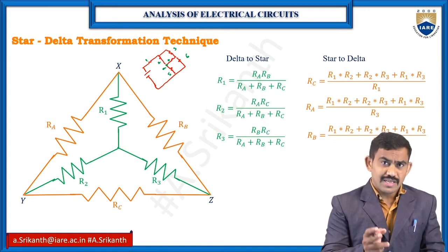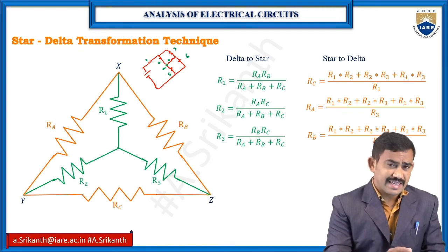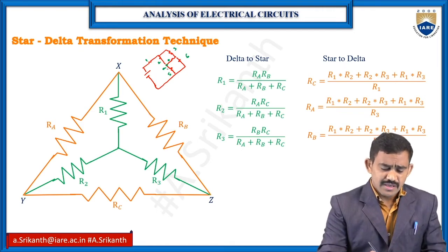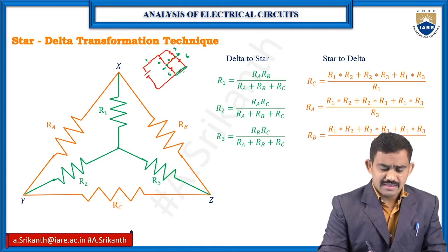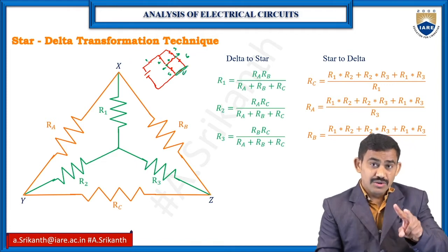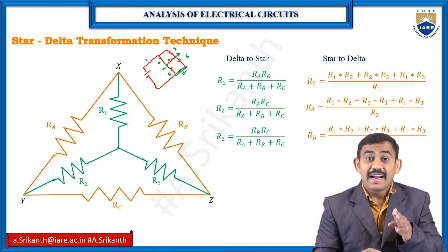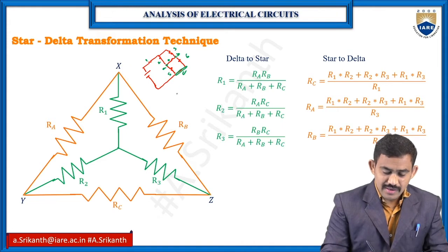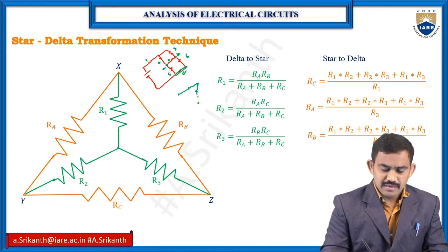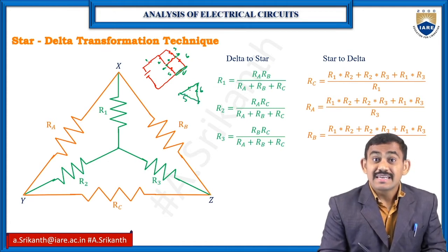First, I will check whether those are connected in delta connection or star connection. Okay, A, and here B, and here I can select C. So I have 3 nodes. In between the 3 nodes, the 3 resistors are connected in delta position: between A, B, and C, the 4 ohm resistor, 6 ohm resistor, and 5 ohm resistor. So they are connected in delta position.